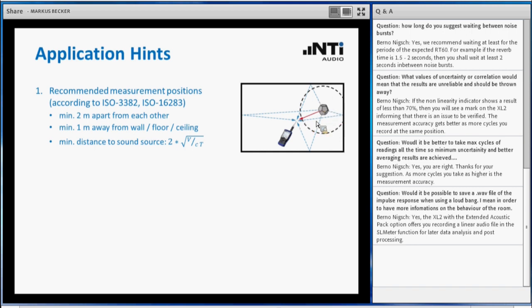I just draw some schematical examples in here, and these reflections sum up also in a certain sound pressure level at the microphone. And the diffuse field starts there, where these reflected sounds are higher than the direct sound from the signal source. And that is where you have to execute the measurement. So outside of this schematic circle around the signal sound source.